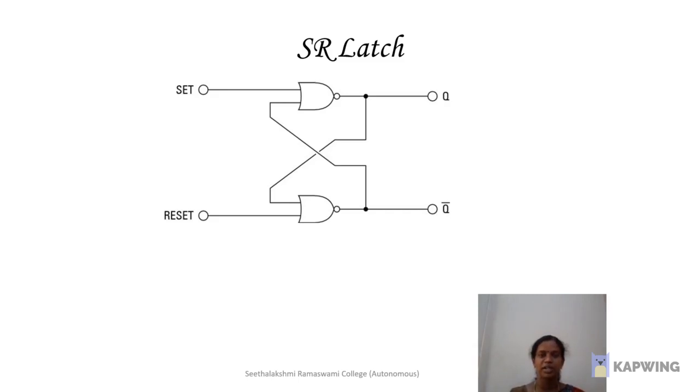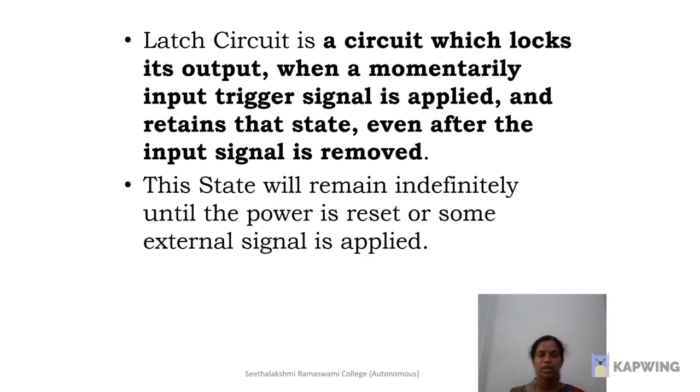SR latch. The set-reset latch can be constructed from NOR gates or NAND gates. With the NOR gates, the latch responds to active high inputs. With the NAND gates, it responds to active low inputs. A latch circuit is a circuit which locks its output when a momentary input trigger signal is applied and retains that state even after the input signal is removed. This state will remain indefinitely until the power is reset or some external signal is applied.